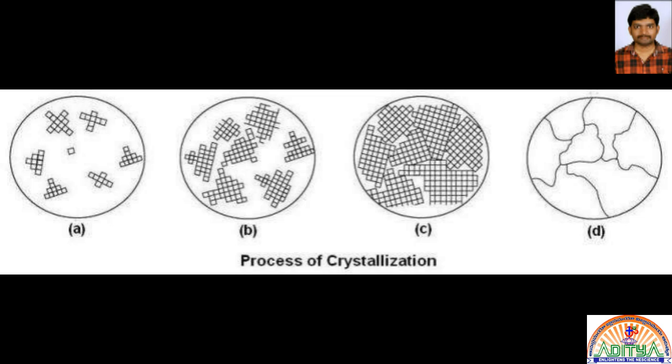It is one important definition in this concept. A slower cooling rate can result in larger crystals, while a faster cooling rate can result in smaller crystals. This is the main important thing regarding the cooling rate. The next step is nucleation sites. The presence of nucleation sites such as impurities or surfaces can influence the crystallization process. These sites can provide a location for crystal growth to begin.